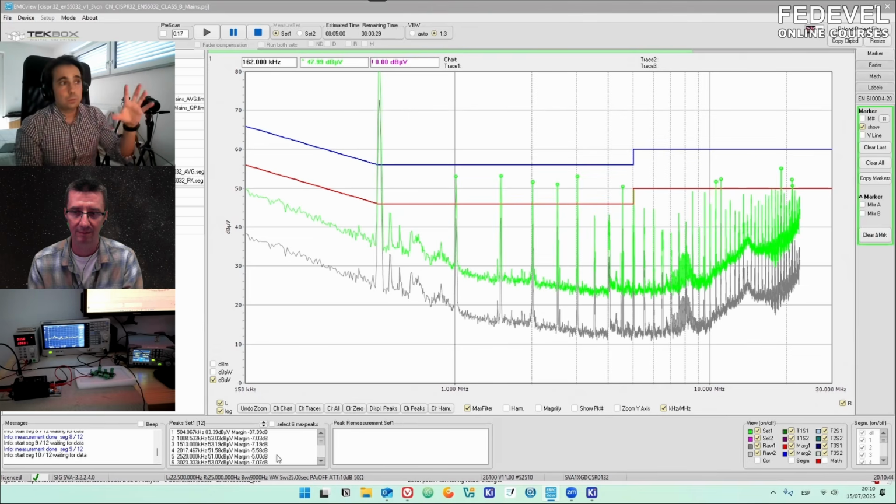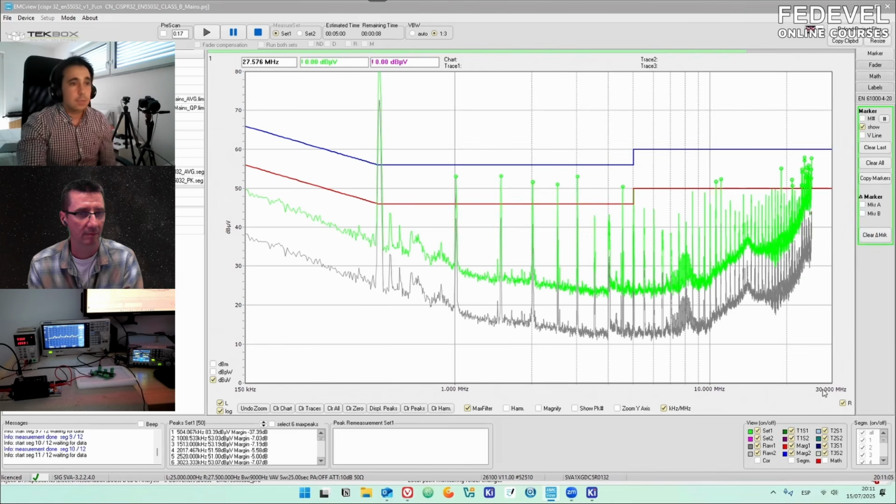There is, at some point, a correlation between radiated and conducted results. So if you reduce most of your problems of conducted emissions, or you attenuate the noise going over the cables, you will already solve quite a lot of things, or you will reduce a lot the risk of failing radiated emissions. Because one thing that you can do, even if it's not the frequency range of the standard, is increasing the frequency range and see if you have higher amplitude in higher frequencies.